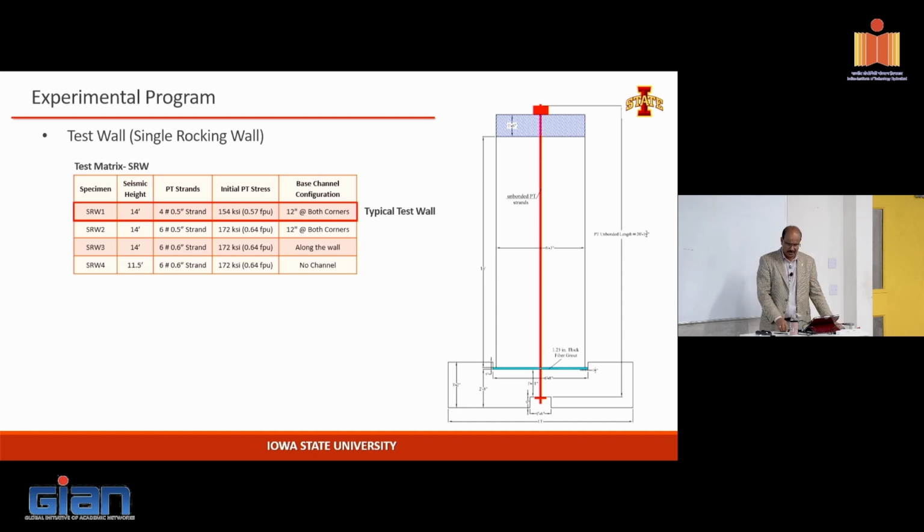Because of the rocking nature, to prevent any damage at the base, in the past people tend to put in steel channels here, so that basically the channel is the one that causes the impact, rather than concrete to concrete. There was concern that if it's concrete to concrete, some damage will take place. So we had an official designer who is a practicing designer. Then we have 2 or 3 precasters who work with us. So they also dictated in terms of erection, prefabrication details, performed the actual prefabrication. They also looked at the detail and made comments.